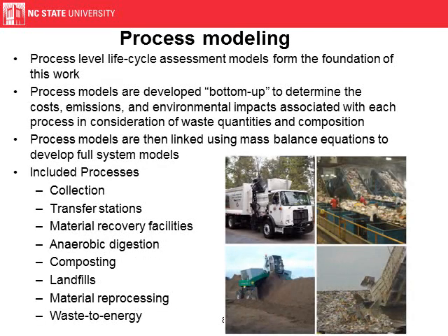Like I said on the second slide, the solid waste management life cycle inventories of each solid waste management process are the foundation of all of this life cycle modeling for solid waste management. The process models we use are developed from the bottom up to determine the cost, emissions, and environmental impacts associated with each process in the solid waste management system, in consideration of the waste quantities and composition going to that process. What we mean by bottom up is that we're looking at all the sub-processes in that process and developing those emission and cost estimates from how all those sub-processes are connected.